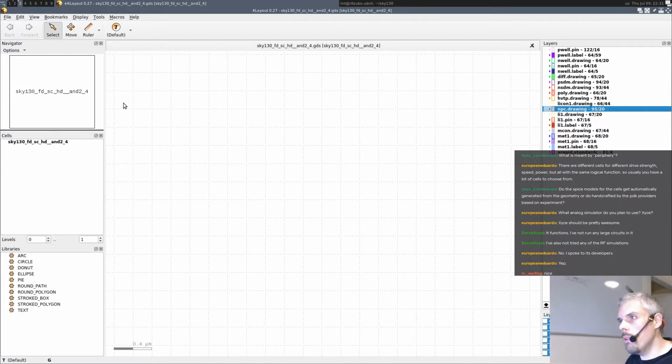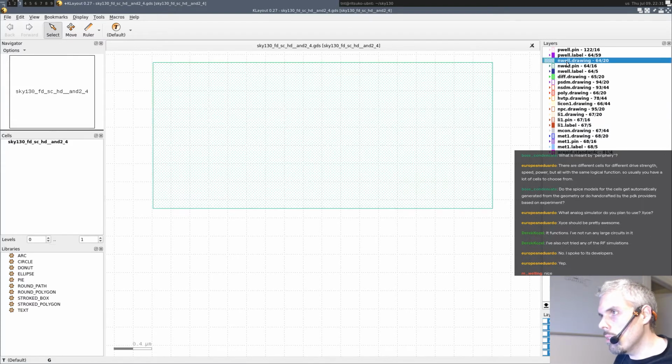So the first step is, since it's a complementary MOS design, like that's what CMOS means, right? Which means you'll have both NMOS and PMOS. So the first thing that's going to be useful is to actually create the N well so that you can put your PMOS transistors. And so that's done using this layer.